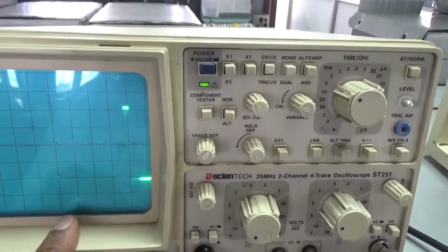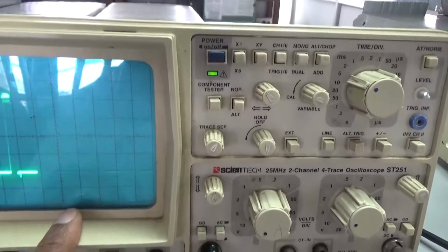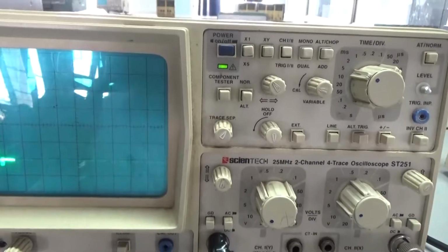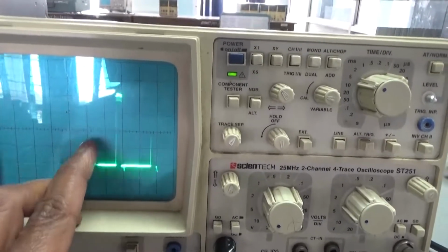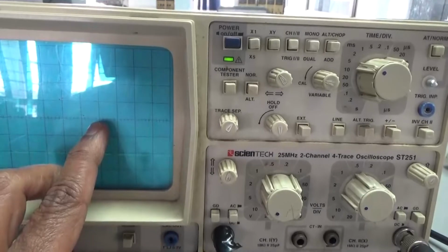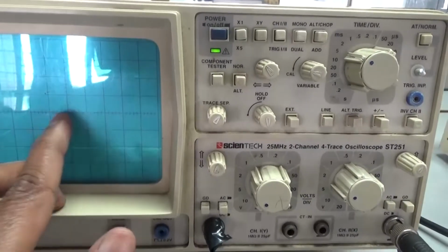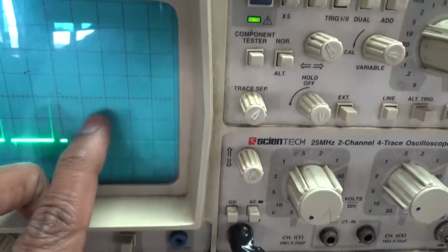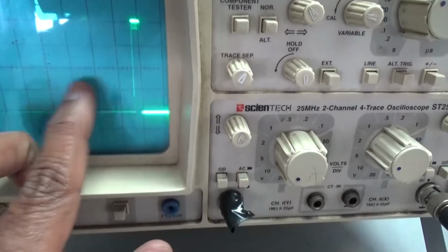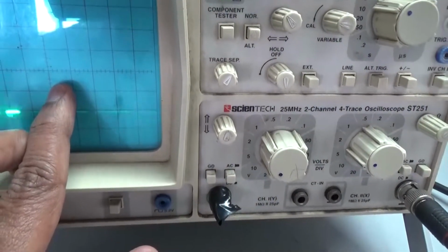So we have turned on the supply. As of now, the firing angle alpha in the CRO, from the zero reference, is 1 unit, which is 5 subdivisions, then 6, 7, 8 subdivisions. So 8 subdivisions corresponds to 18 times 8, which is 144 degrees. That is the firing angle as of now.